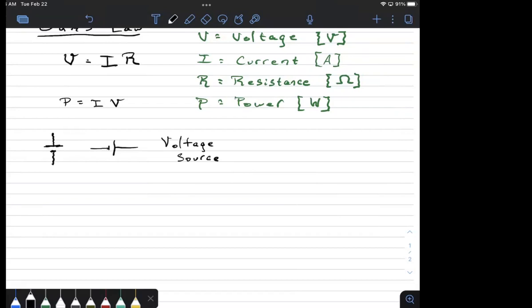And the other big symbol you need to know is the resistor, which looks like this jaggy, spiky wave looking thing. And depending if I draw it vertically or horizontally, that's what a resistor looks like. Then all you do is connect these symbols together in whatever way is necessary to represent the particular circuit you're talking about, using lines, and those lines represent the wire of the circuit.